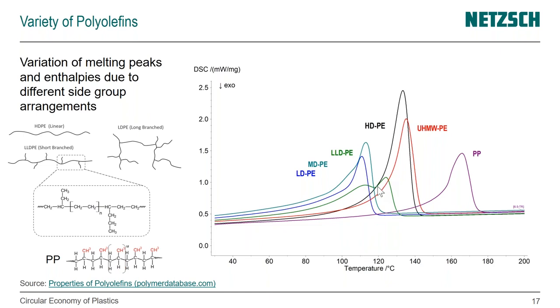And that has to do with the branching and the configuration of the material and how closely it can pack. And the crystallization behavior. So you can see that in the crystal growth and crystal growth speed. Those are all effects that you can look at also with DSC, but that's more a general analysis of polymers using thermal analysis topic, I think.